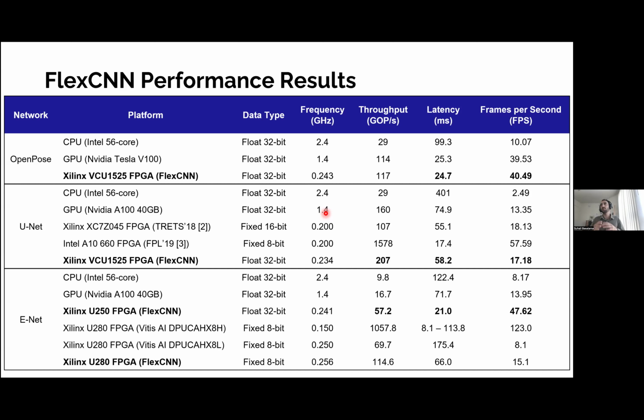Theoretically you can create an ASIC or a design that supports CNNs only, or one that supports CNNs, transformer models and multi-layer perceptrons. But my general idea is that the more flexible you make your accelerator, the more you lose on performance efficiency and power efficiency.